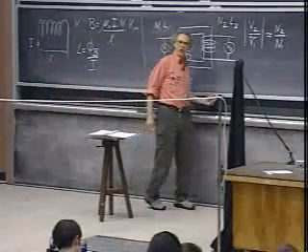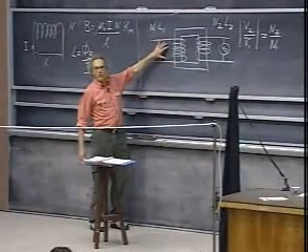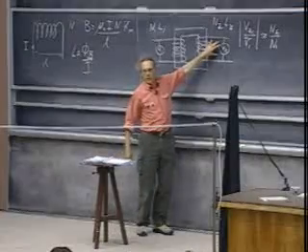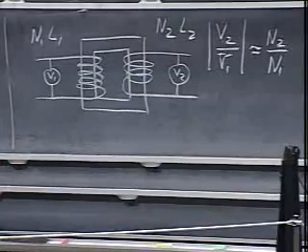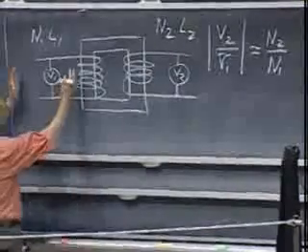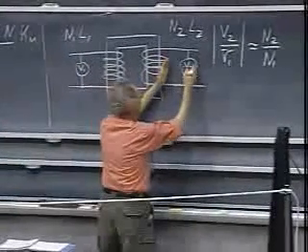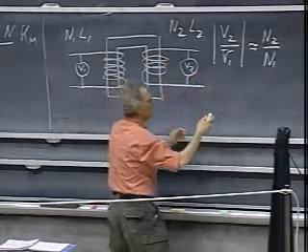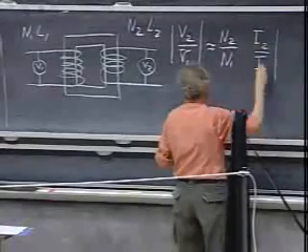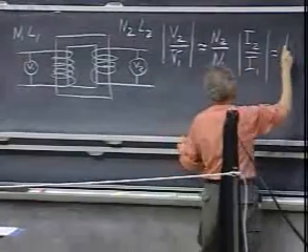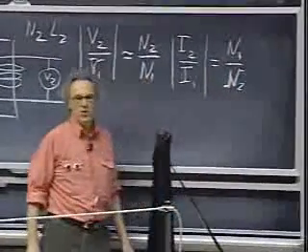Under very special conditions, the power generated on the primary side will be all consumed, for 100% or nearly 100%, on the secondary side. That is very, very special. If that's the case, then the time averaged power here, V1 I1, is the same as V2 I2 here, time averaged. And so as a logical consequence of that, you'll find that I2 divided by I1, let's not worry about minus signs, is N1 divided by N2. That, however, is not so easy as you may think.